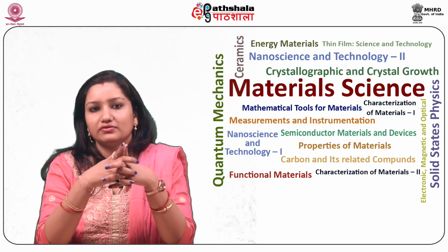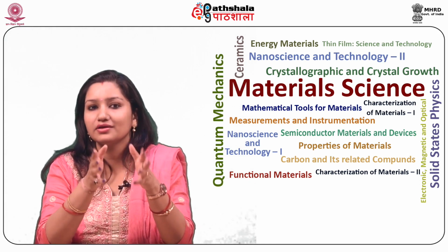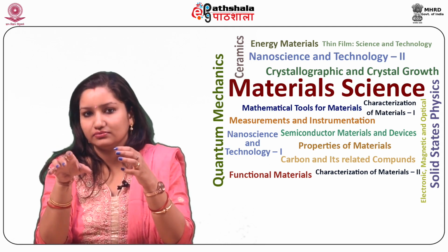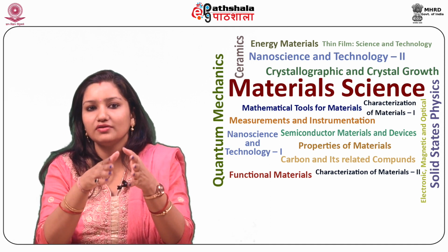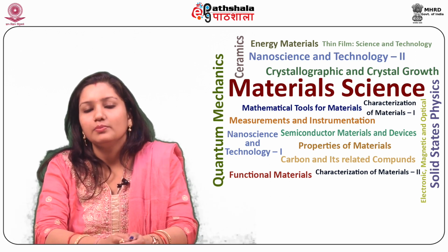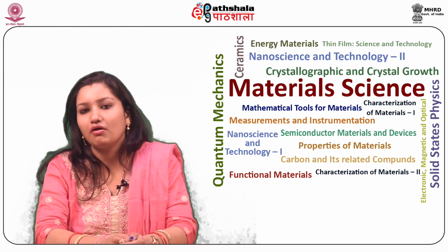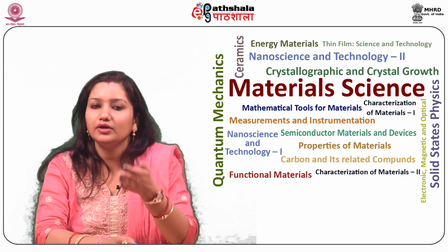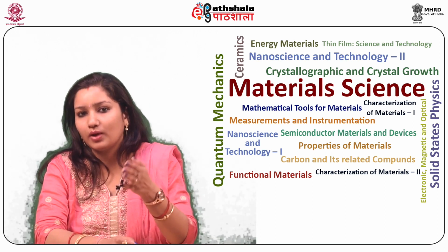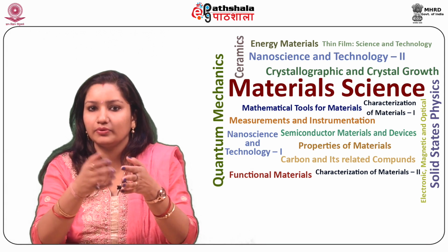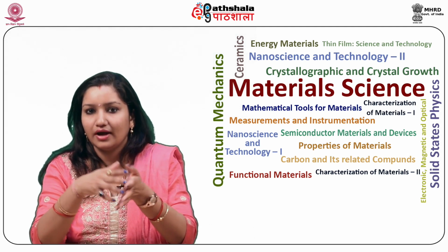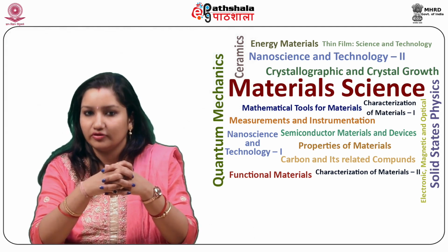So the main advantage is the monocrystalline solar panels have the highest efficiency rates since they are made out of the highest grade silicon. The efficiency rate of the monocrystalline solar panels is typically 15 to 20%. SunPower produces the highest efficiency solar panels on the US market today. Their E20 series provide panel conversion efficiencies of up to 20.1%, which was updated in April 2013. SunPower has now released the X series of solar cells at a record-breaking efficiency of 21.5%.